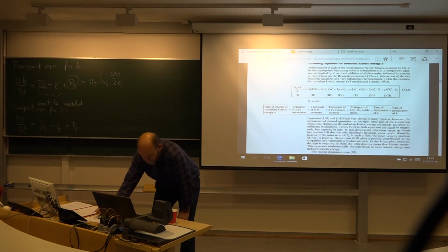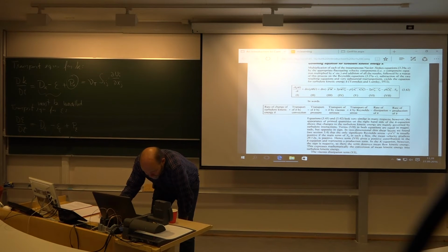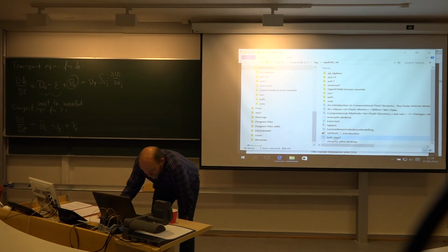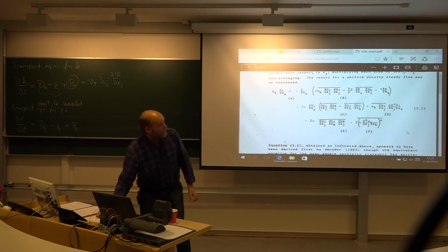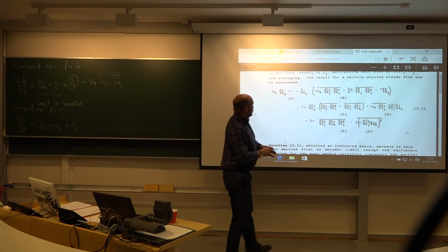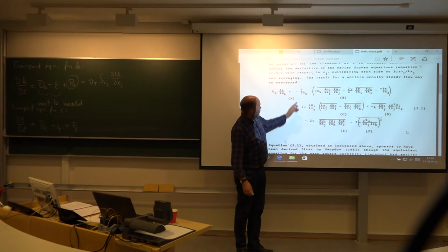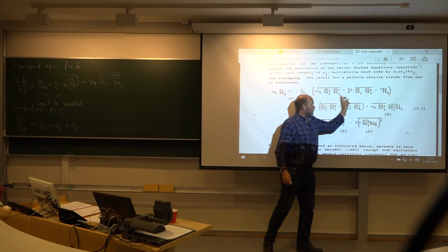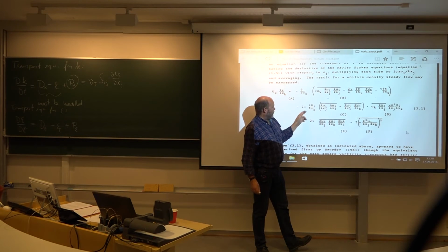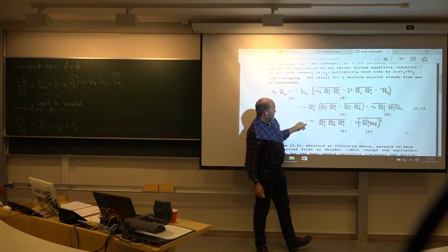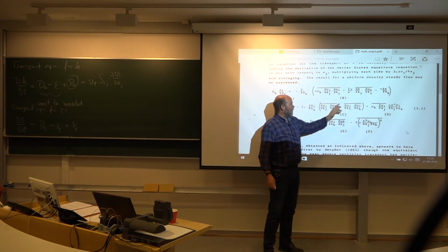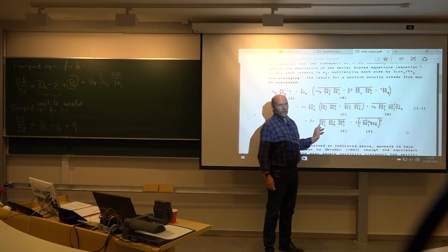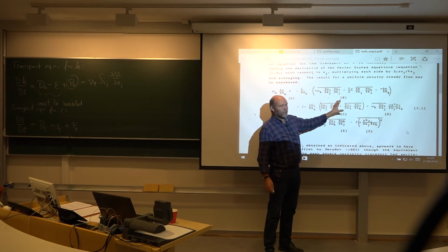Because I think I brought it with me, I can show it to you. The exact transport equation of the dissipation looks something like this. And here you have a derivative in front, so this is a diffusion term. And then you have the viscosity in front here for a couple of terms, which should then be dissipation, and then finally a production term. And of course, they are getting more and more complex. Just forget it. You can't model these out of these analytical expressions.